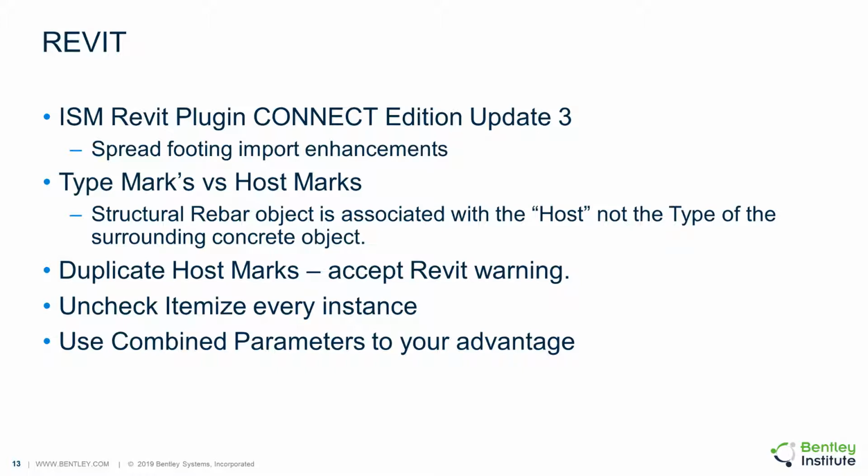And also use combined parameters to your advantage. So besides just showing the dimensions of our spread footing in individual columns in our tables or our schedule, we can combine these parameters into a reinforcement callout or bit of text that's easily understandable. Okay, so let's see that in action.